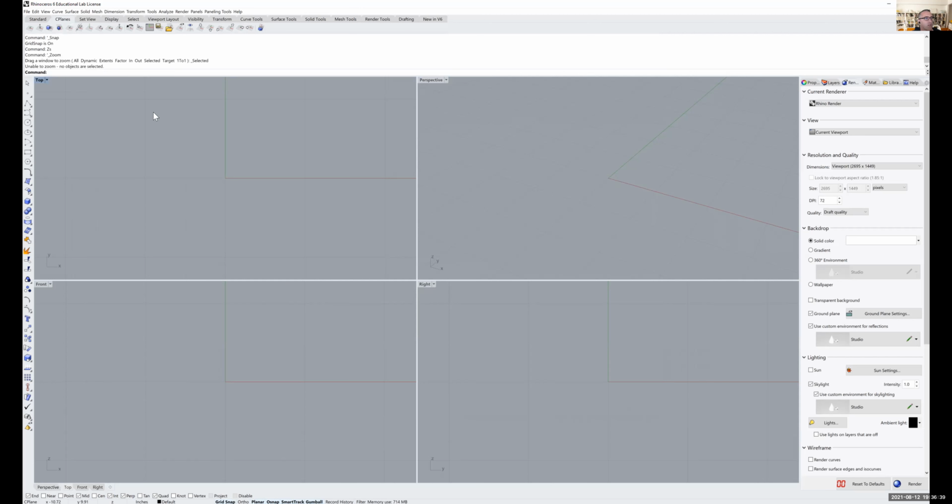Oh, so here's a really good one. Let's change it for you, and I'll show you how to do it. I told you guys last night, I love zoom selected. It's a really great tool. To set the alias, what you want to do is find the command that you want, like polyline a second ago, I said I would initiate it. And then you can see where it says command and it says polyline. What you can do is Control C, and then we can go back to the aliases and paste that in.